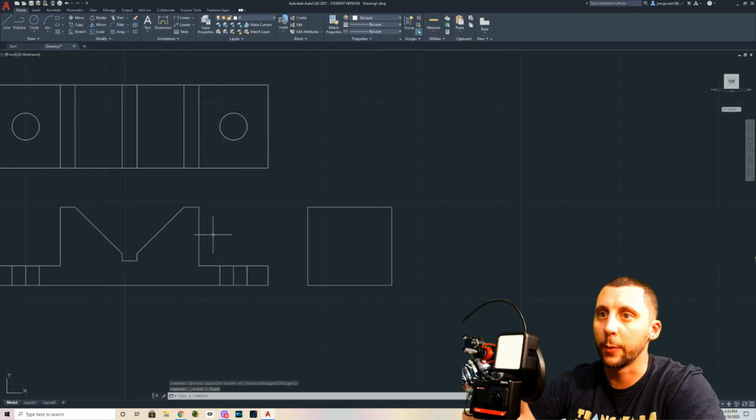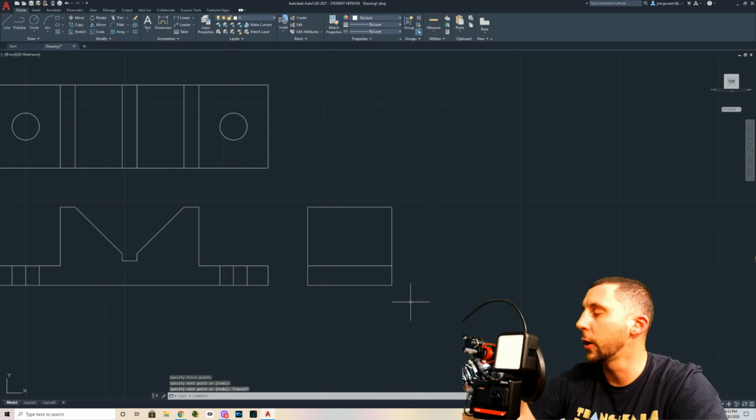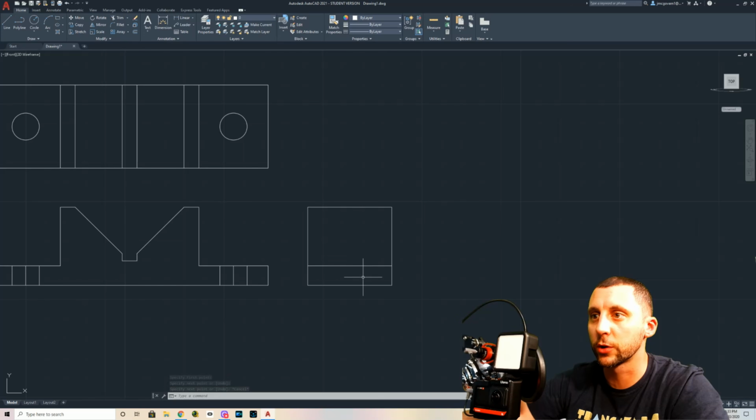Now, this is a step. It's a step up. There's a big crease here, or a bend. That means that I have to show that here. Okay. We also have to describe all of this. This would just look like it was just straight up over, but there's a big notch missing, or a big piece cut out at the top. So we have to describe that in that view. Where does it bend? How deep does it go? Well, the depth of this is all the way down here.